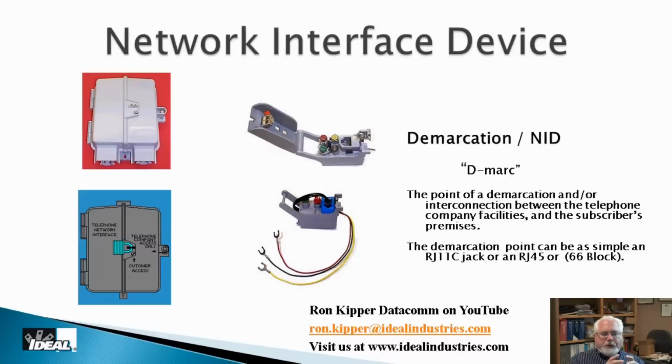Okay? Now, when you look at this gray box, it's split in half. Half that box is the telco side of the box, and technically you're not allowed to get into that. Now, you'll find a nut driver will open it up pretty quickly for you if you want to take a look at it. And you're going to find nothing but a simple connection going from their side of the box and plugging into this thing on the customer side of the box. And that's the actual physical demarcation point, that right there. And that is actually a testing point.